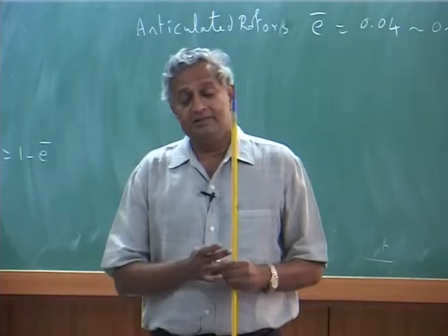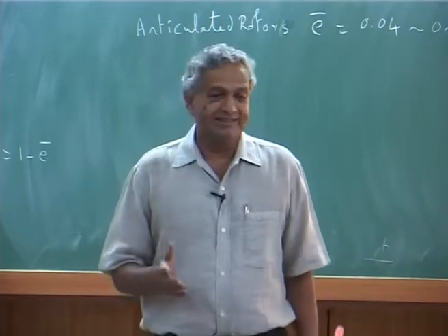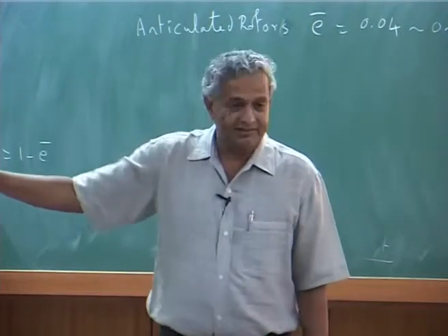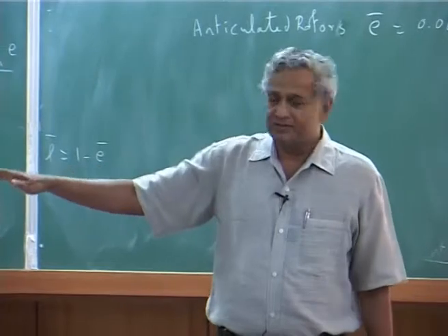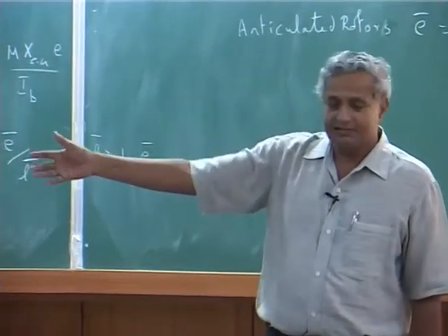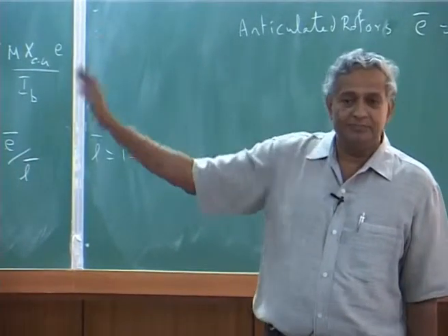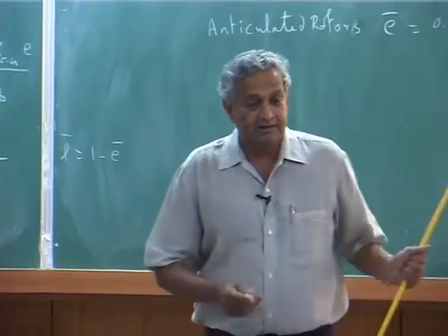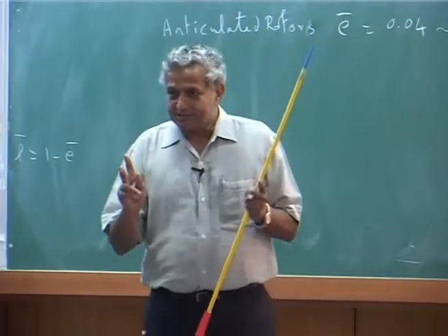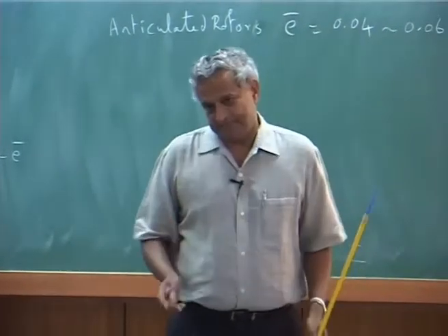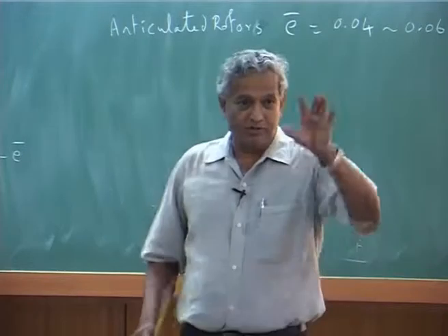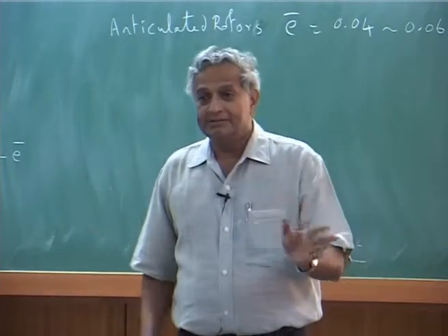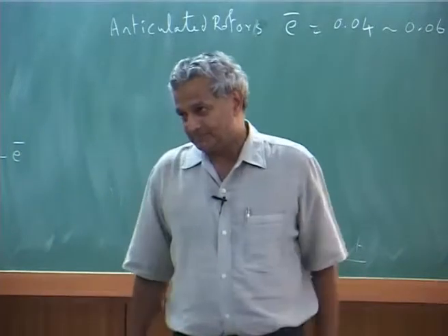You do not face that kind of instability in the fixed wing, because there you only take torsion and out of plane bending. Here two bending motions can make the blade unstable. Now, for you to analyze, you have to solve the coupled flap lag aeroelastic problem.